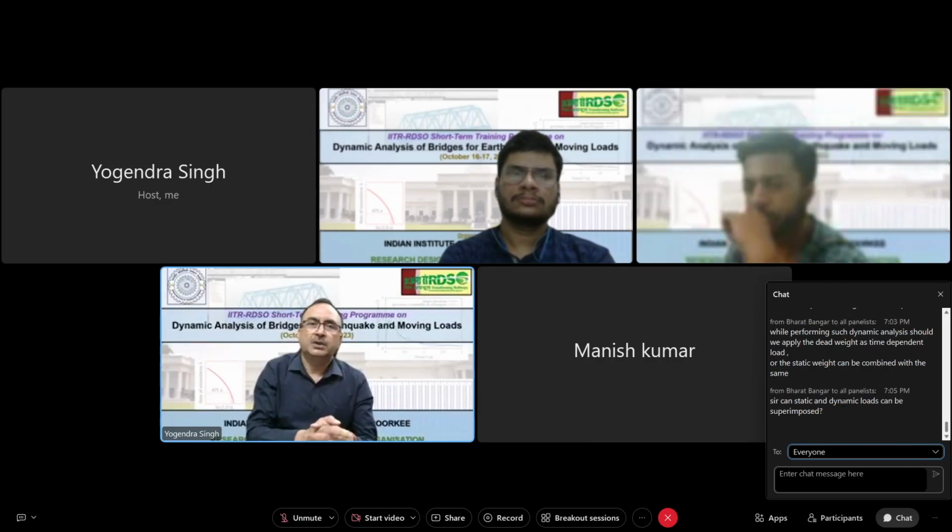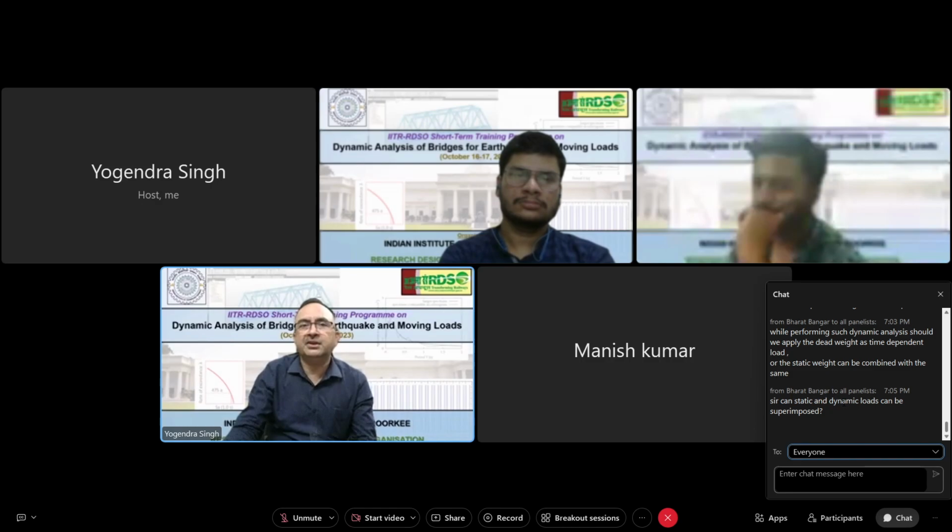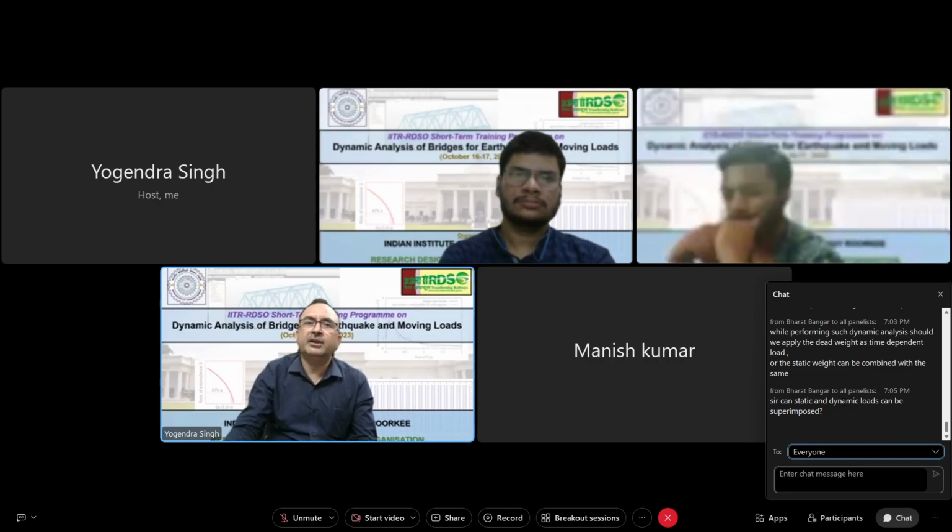Problem will occur in case of nonlinear analysis, because nonlinear analysis depends on the history of application of the load. So there we have to first perform a static analysis under dead load. Then whatever are the results of this static analysis for dead load, we will consider as the initial conditions for nonlinear time history analysis.